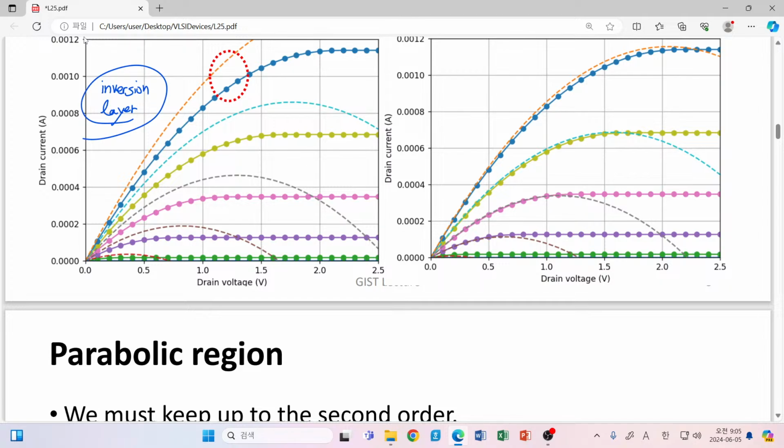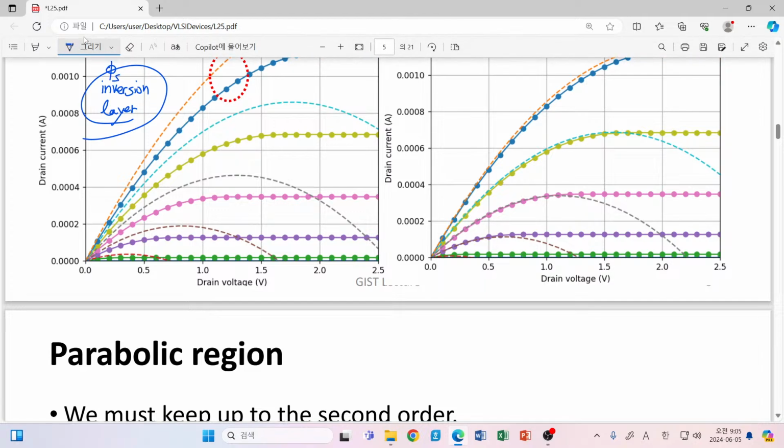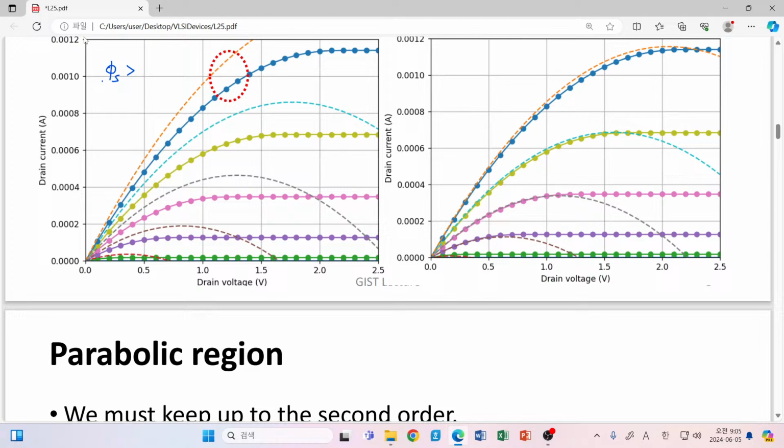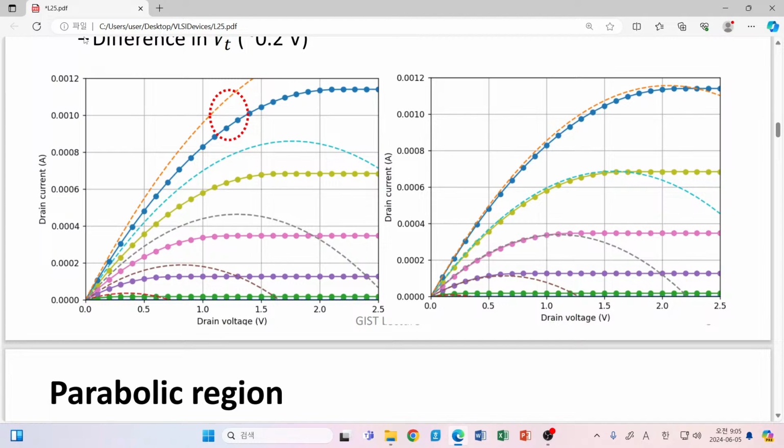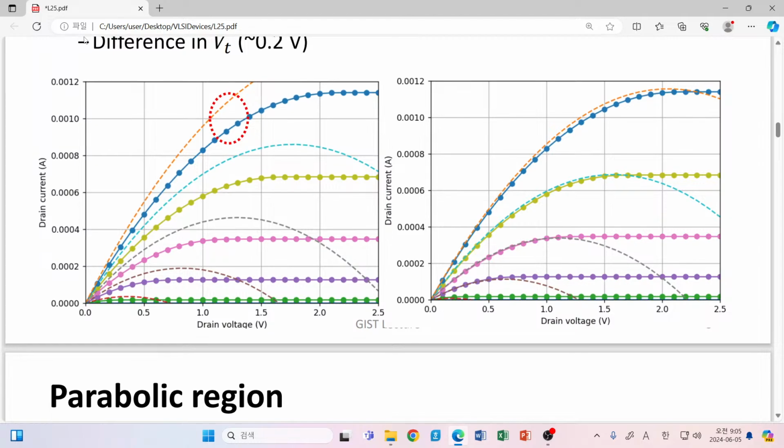So in order to have a sufficiently high electron density, actually we must increase our surface potential a little bit further than just 2 times phi B. However, that effect was not considered in our present expression. That's the reason why we have a slight underestimation of our threshold voltages. So by making a simple calibration, then we can have a much better one.